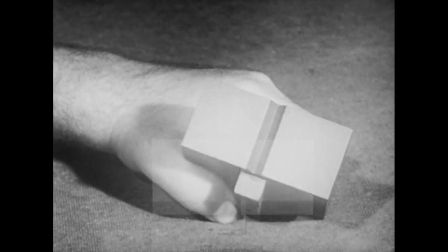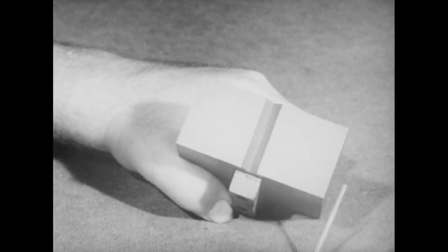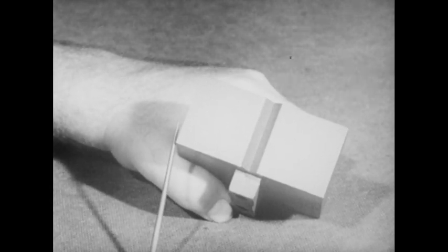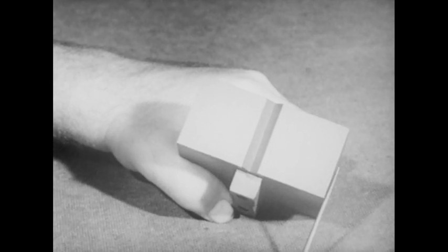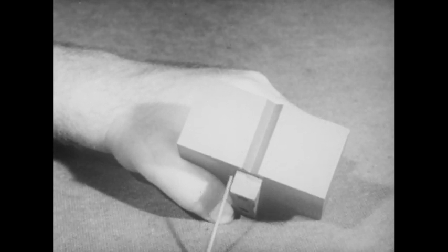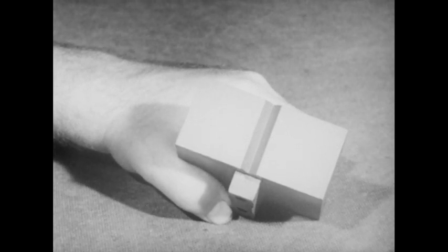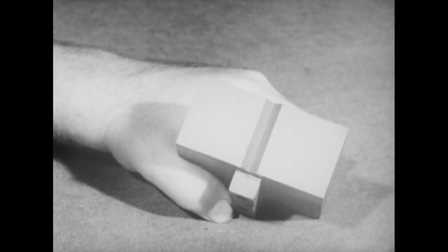Imagine that parts of the bed can be removed so you can see the movable jaw tongue. Notice how it fits into the slot and slides back and forth. These mating parts, the tongue and the slot, must work together. Give direct, positive dimensions for them, correlated so that the parts will fit. Do not ask the machinist to subtract this dimension and this dimension from the overall dimension to get the width of the tongue, because a dimension given indirectly is less accurate than a direct positive dimension.